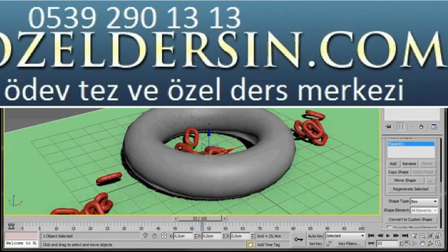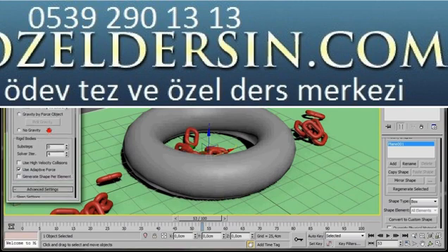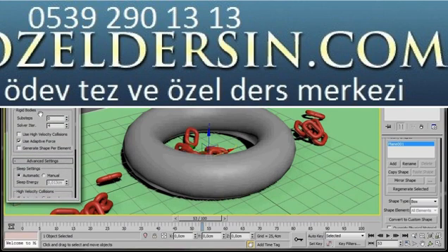Let's go back up to the toolbar. And now we're going to click on the tools. Now here, let's have a look on the panel. Make sure we have the use ground collisions turned on, the gravity set to the Z. Okay, then let's have a look here in the rigid body. We'll adjust the sub-steps and solver iterations. I think I'll type in 2 for sub-steps. In the solver iterations, I'm going to type in 20. Then let's go back up again to the toolbar and press reset, just to bring everything back again.